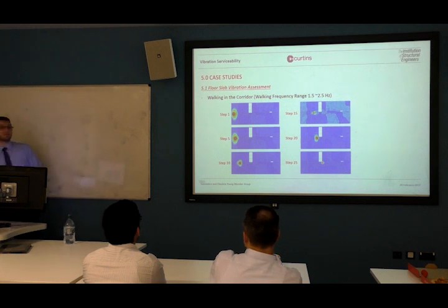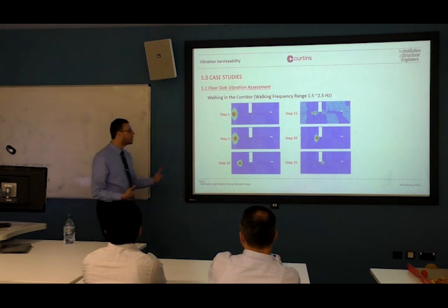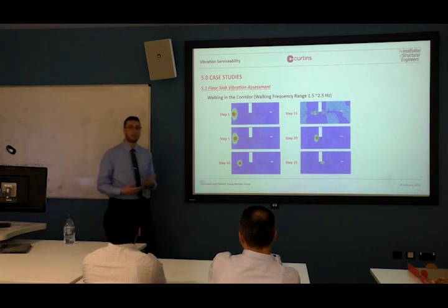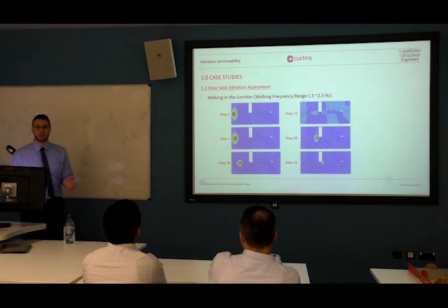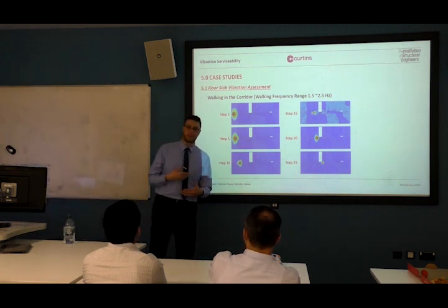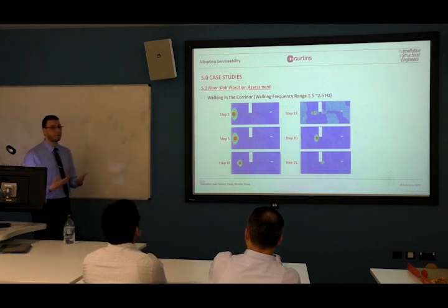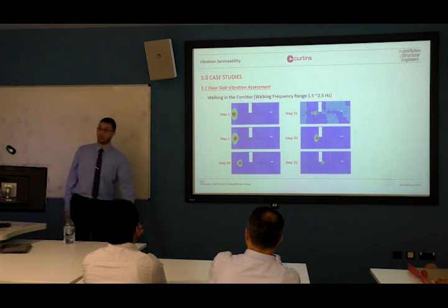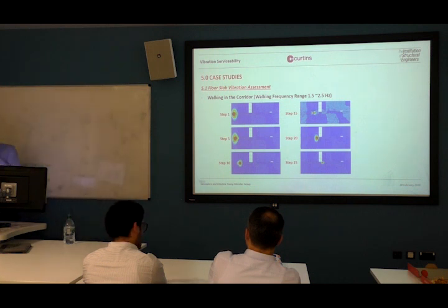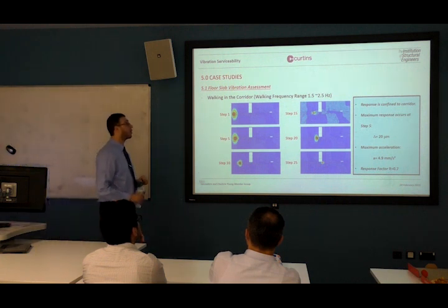And when we talk concept design, we have to take concept design in dynamics as well. This is the concept design we talk about: the way you distribute your columns. It's not like, I'm going to get 6 meters, 7 meters. You have to think about all these aspects of loading that you might get, and the way you distribute your columns, the way you put your structure mass, makes a lot of difference actually. So the response, as I said, is very confined to the corridor.